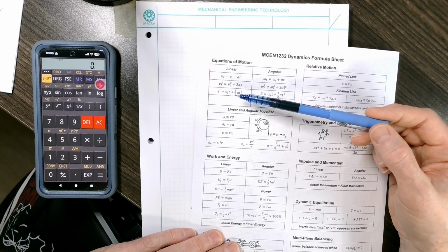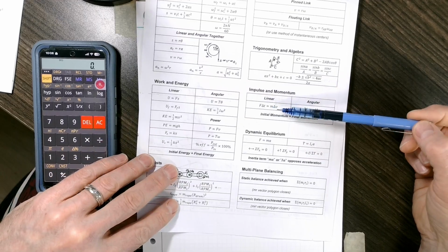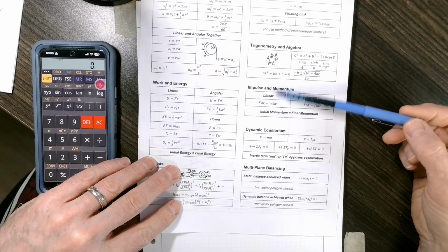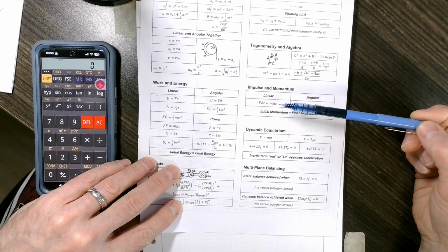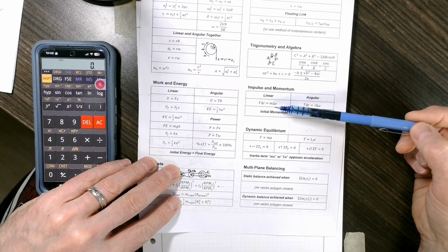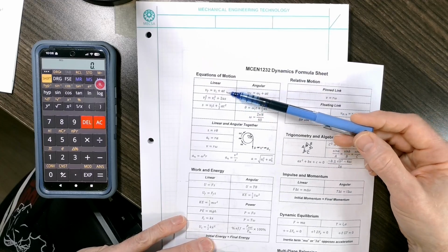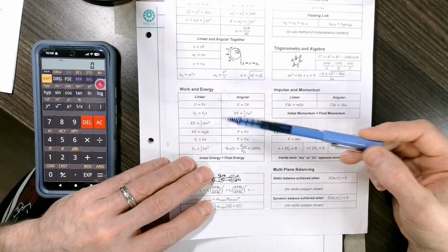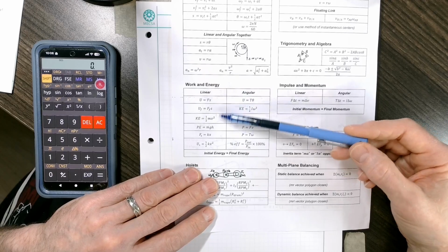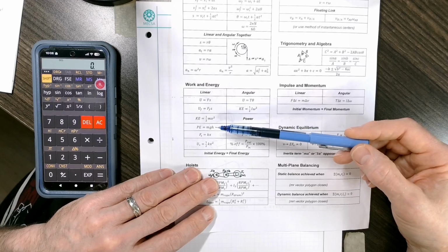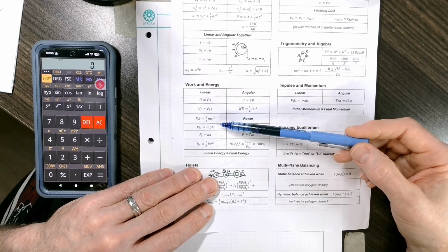In other words, if you have a problem and the initial data you have is time and velocity and applied force perhaps, go ahead and work the problem using the impulse momentum method, obtain the unknown, time or velocity, or maybe force, but time or velocity, and then follow up with kinematics if you want to know displacement or acceleration. Similarly, if you have in your initial data acquisition velocity and displacement, then the work energy method is a nice easy fit. So use that method and obtain an unknown, either the final velocity or the final displacement.